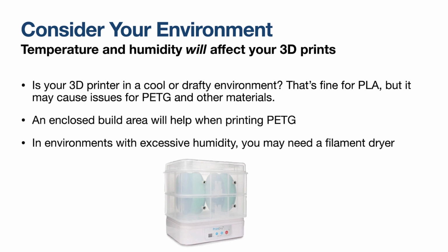And an enclosed build environment can help, especially with some of these more advanced materials, PETG, ABS, polycarbonate, the ones that tend to warp more. You really want to have an enclosed build area for that if you can. That's going to help quite a bit.